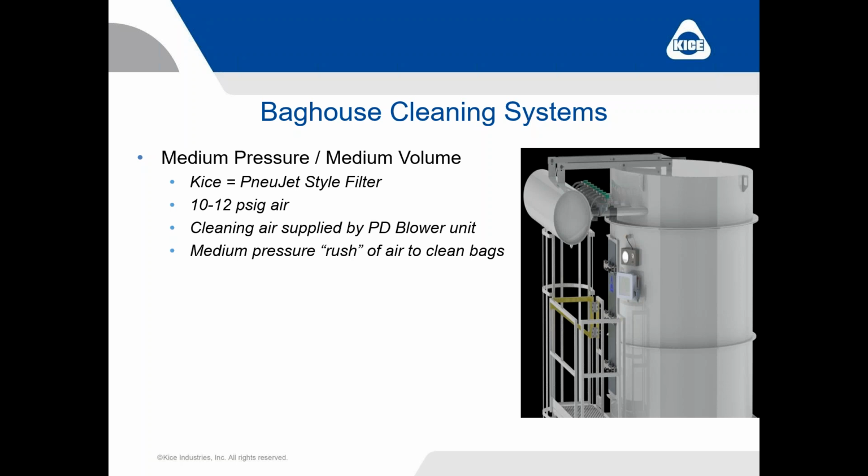So we'll have a blower package hooked to that air tank. We're going to let that air tank build pressure to about 10 to 12 psi, and then our timer board is going to tell each blast valve one at a time when to fire down. So we're using a lower pressure of air, but a larger volume to rush or help flood the dust off of those cleaning socks. Same goal and largely the same effect as that high pressure pop, just a little bit different way of cleaning those bags.